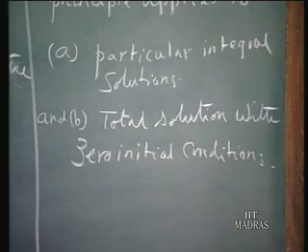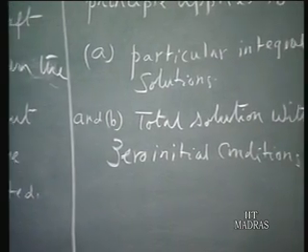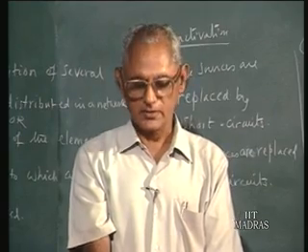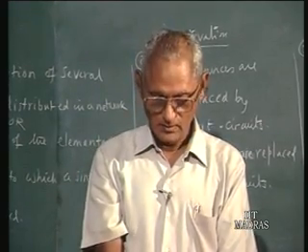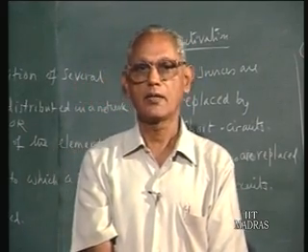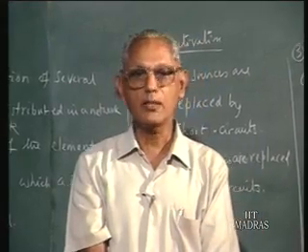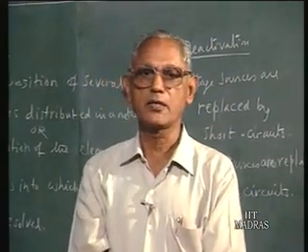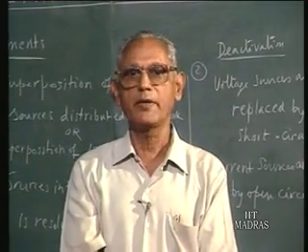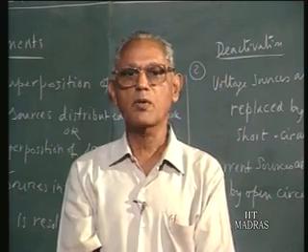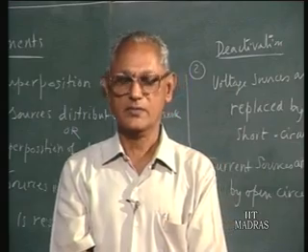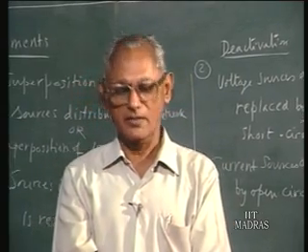This is because when you have an initial current in an inductor or an initial charge on a capacitor, it spoils the linearity of the terminal relations between the voltage and current in an inductor or a capacitor. You may recall that all such non-zero initial conditions associated with inductors or capacitors can be replaced by equivalent independent sources, either DC sources or impulse sources, and the Laplace transform domain analysis incorporates such equivalent sources to replace the initial conditions.